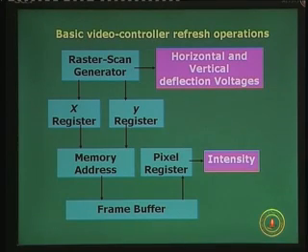So, it is almost a must in most modern day systems to have a separate display processor which runs the graphics application programs and the packages and accesses the display processor memory or the frame buffer to make the display list, the display program, which in turn will be driving the video controller. So, that is the job of a display processor. Job of a video controller, it is very important. Remember from the previous diagram, if necessary we will revisit it again, it basically gets the input from the frame buffer and drives the monitor.